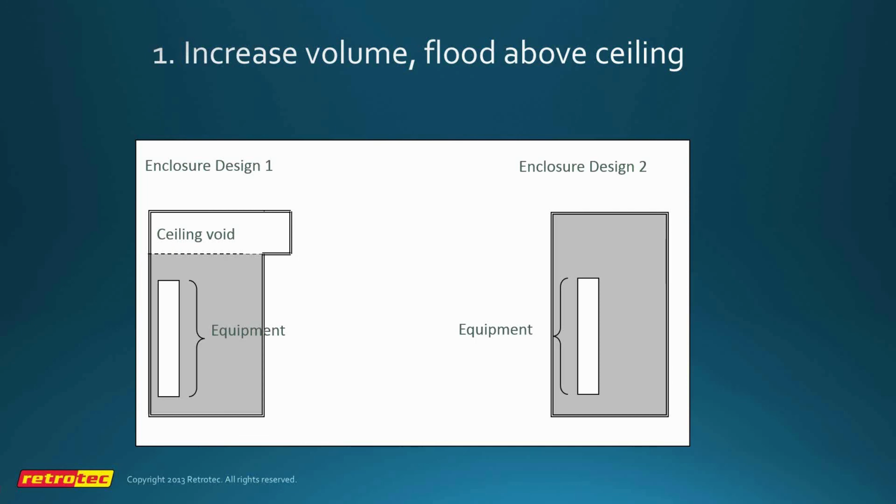The reverse is true with NFPA, where for a typical enclosure, we have to hold to, let's say, 75% of room height, so we can lose a lot more agent for descending interface. It's not true with ISO. So I was actually surprised to discover that even if we put in a low concentration of agent, the continuum mixing still outperforms descending interface by a wide margin.